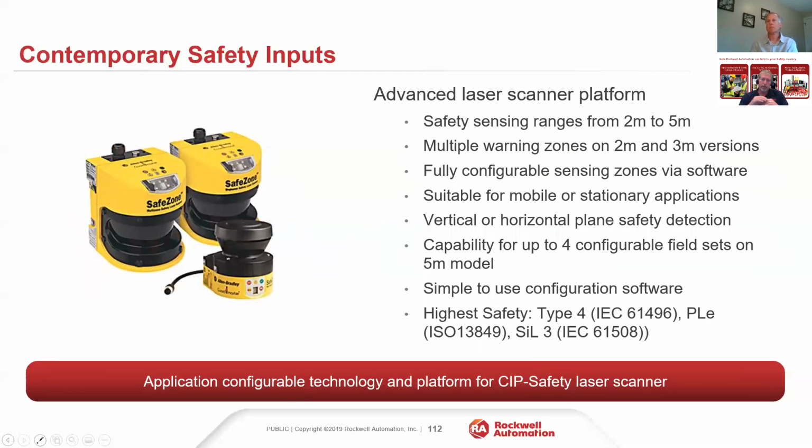Couldn't be complete without mentioning the laser scanner as a contemporary solution option. In many cases, there are folks that are using safety mats that may benefit from using a different technology. Not to say that there's anything wrong with safety mats. They are electromechanical. In some cases, they are a better solution based on dust, dirt, debris, etc. There are reasons why we still do need to use some of the more conventional methods.